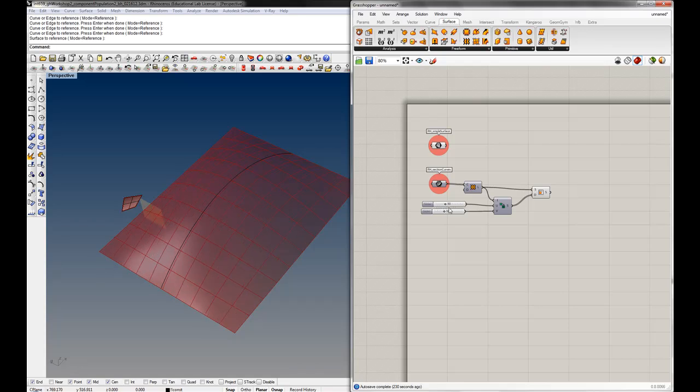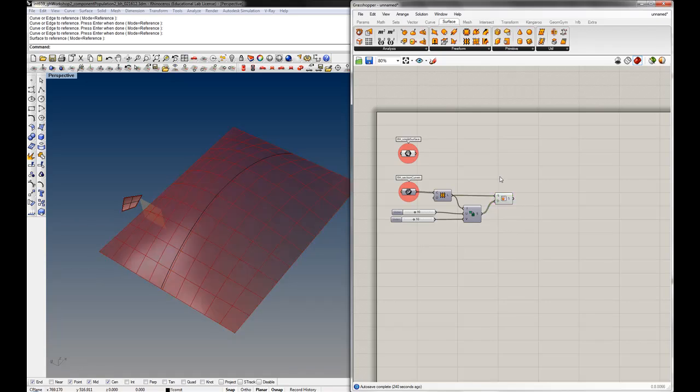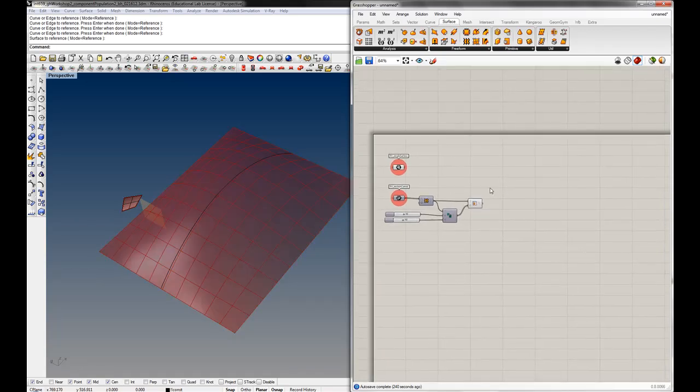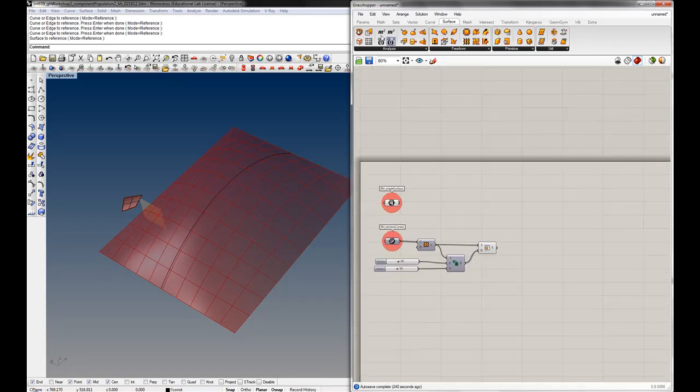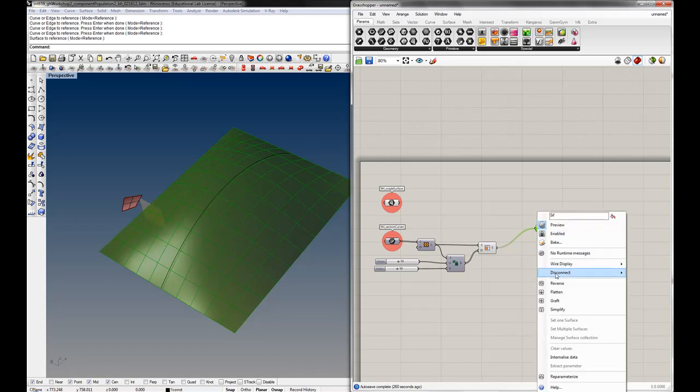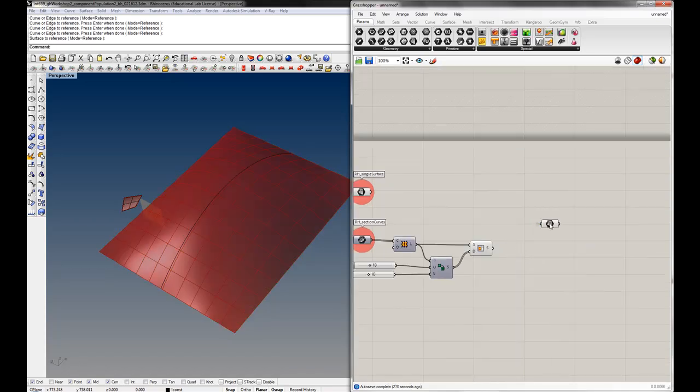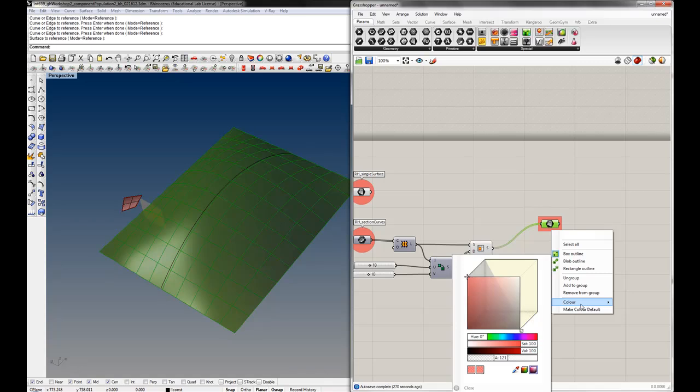Okay, we're getting close here. The last thing we'll need is a server for this function, is what I always call it. Since we're going to be looking for surfaces downstream, we'll go to Params, Surface, and connect all of those into that. Now this is going to be our server. So I always hide the wires, right-clicking and choosing hidden display, and I'm going to group it with Control G. I'll change the color to an orange like we saw.